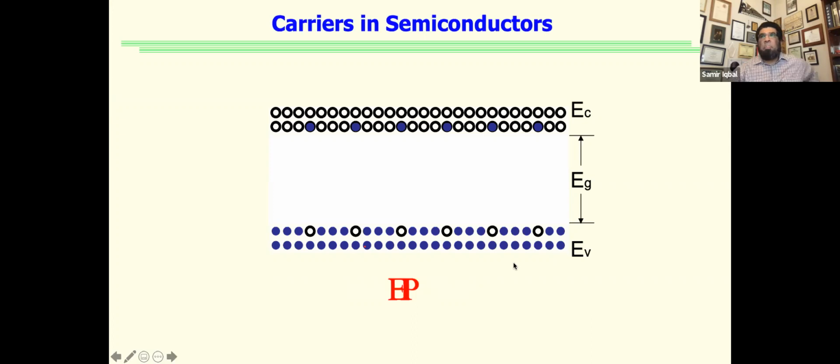Why is it not doing that? So yeah, the animation runs up to 300 Kelvin. By that time, you have many electrons available in the conduction band. But then one can say, okay, if there are so many electrons available, why don't we just use them as is in our devices? Even though there are many electrons, we want a continuous supply. We cannot depend on temperature. You cannot depend on your device to work only if the temperature is suitable. So we don't base the conductivity or charge only on heat.